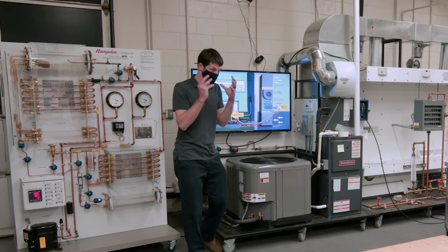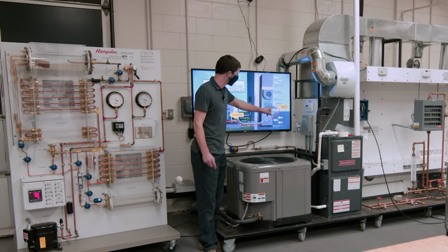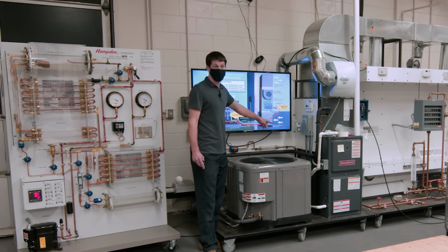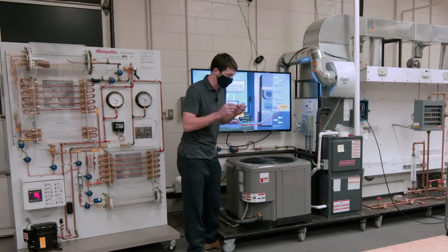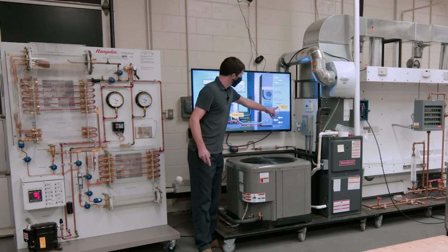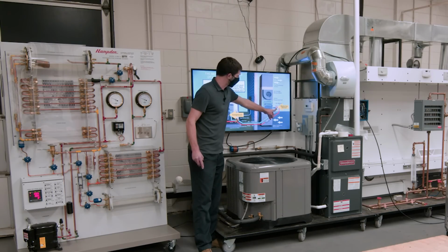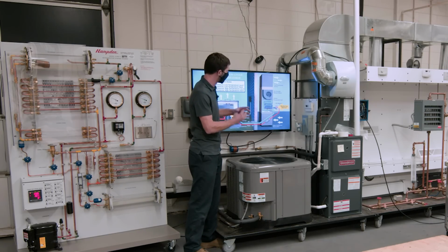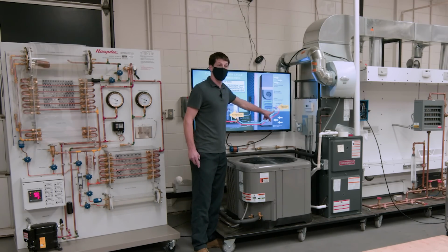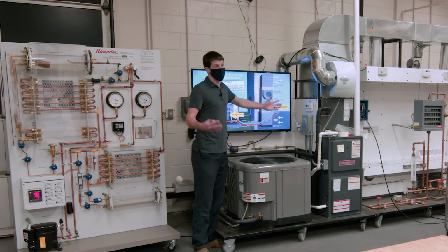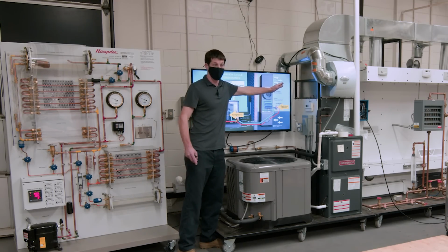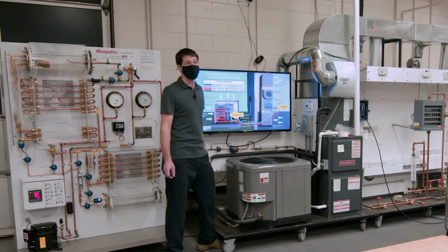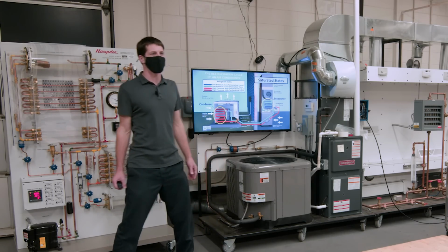If it's like a huge heat load in the building, it's going to exit way hotter than it needs to be. And so this thermostatic expansion valve is going to be able to open up and allow more subcooled refrigerant. It's going to lower the temperature because of the pressure reduction, but it's going to allow more refrigerant in here. It's going to hold the superheat, so maybe it's 52 degrees here instead of 70 degrees here. And so you've got to think if it's a lower temperature refrigerant that exits the evaporator coil, it's going to be a lower temperature air that's going to exit through the supply plenum. Does that make sense? Or it might not have been a great explanation. I don't know. Go ahead.